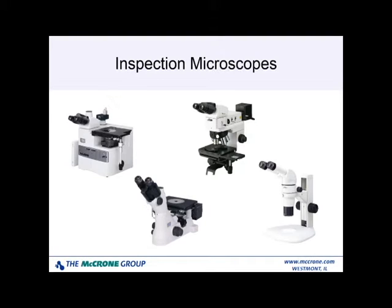This is an example of what inspection microscopes look like. These first two here on the left are inverted materials microscopes. The objectives sit here under the stage. You place your specimen here on top of the stage and view them through the eyepieces. You can use a variety of different optical techniques, bright field, dark field, Nomarski, and on many of these you can also mount a camera system.